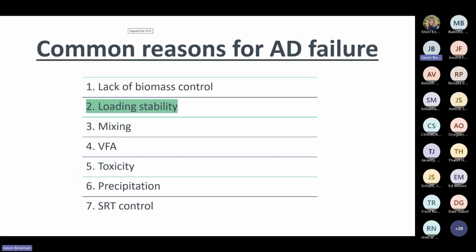Also, conversely, sometimes incoming feed is not available, or maybe a factory or a feedstock is off for the holidays, as an example, and isn't physically producing waste. So you as an operator are not physically getting waste into your digester system. Either way, periodic underloading or periodic overloading can shift the balance of the biomass and potentially create a snowball impact for operators. They start chasing their tails to try to manage not having enough food or having too much food.